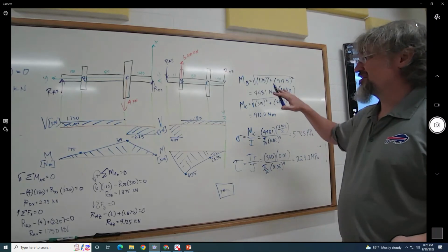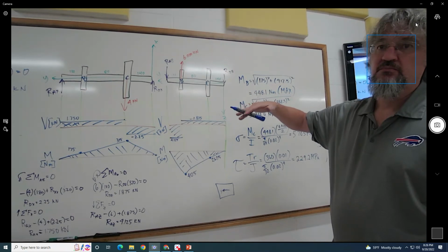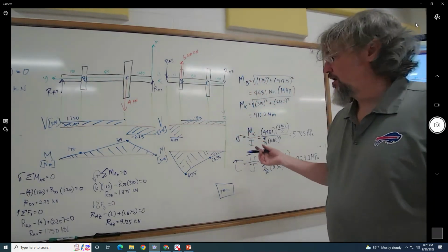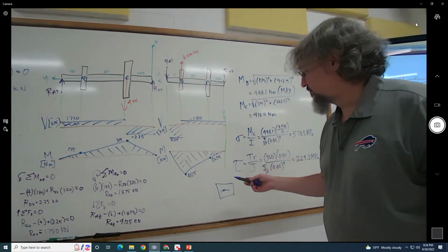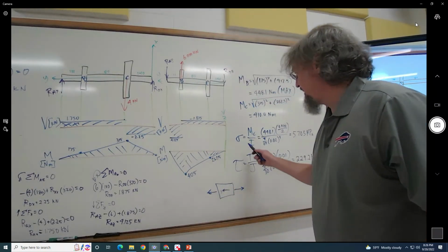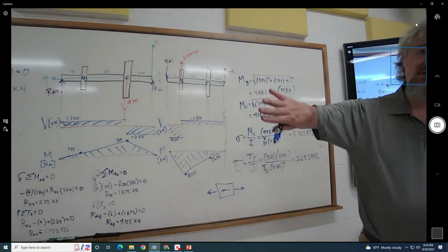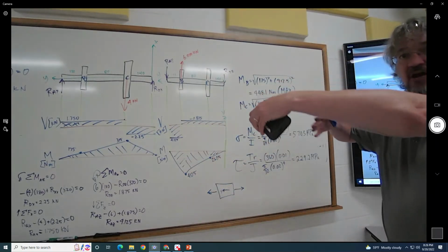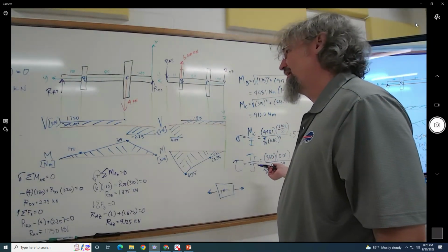And because of this moving plane, we decided to ignore transverse shear, just because it turns out it's not going to be a whole lot, and it's a longer thing than is necessary to do. It's just not worth it. And this bending would actually be tension and compression. Tension on one side of the shaft, compression on the other. If we had a pool noodle with us, we would be able to see how that's bending out of those two planes. And then we could start picking it.